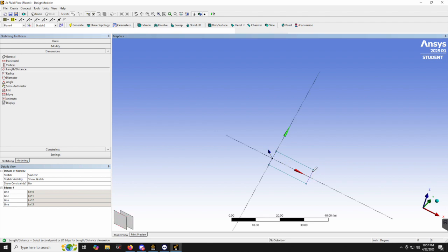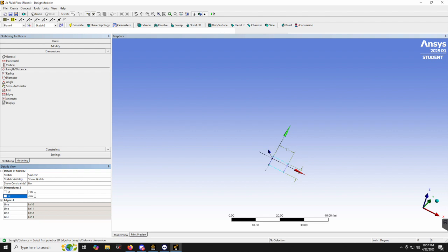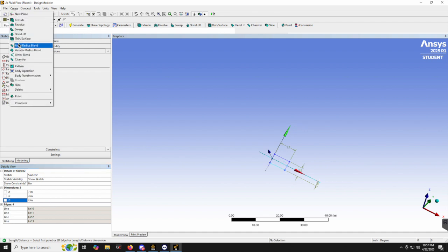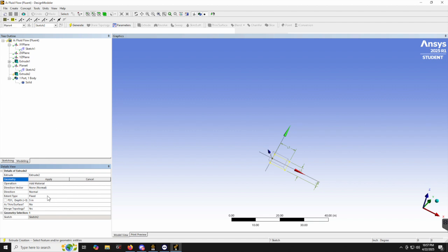The propeller has a radius of 7 inches, and we will do a width of 4 inches. To center it on this axis, I will create this dimension with 2 inches. And I will go ahead and extrude this symmetrically, 3/8 of an inch in either direction.